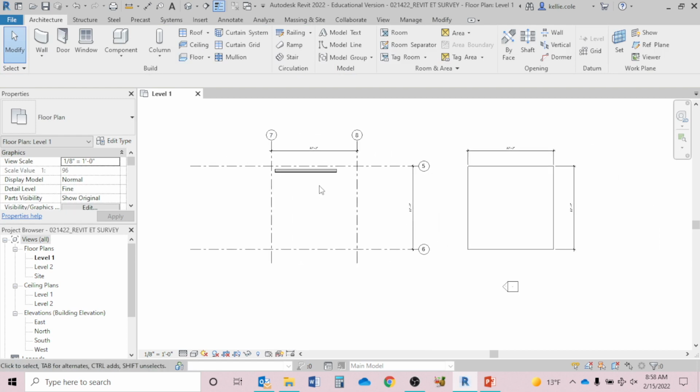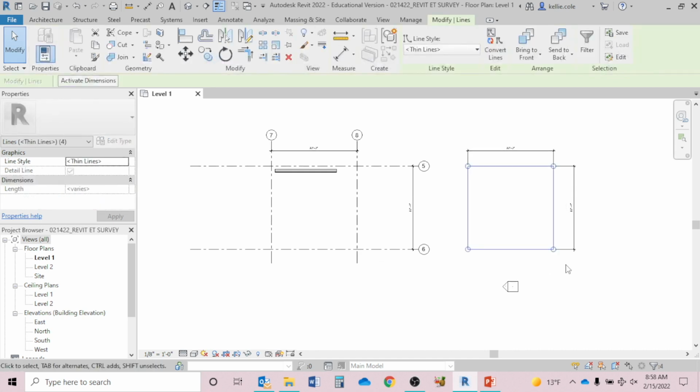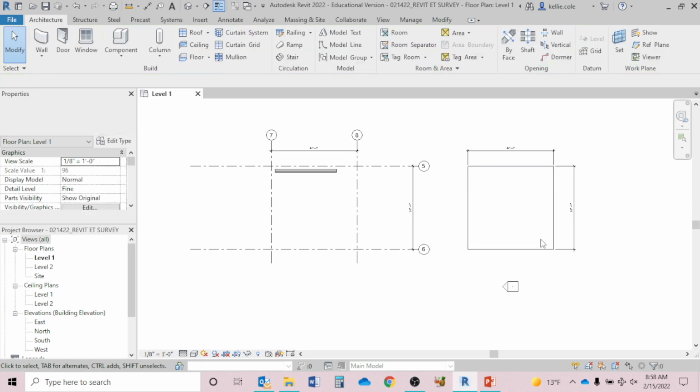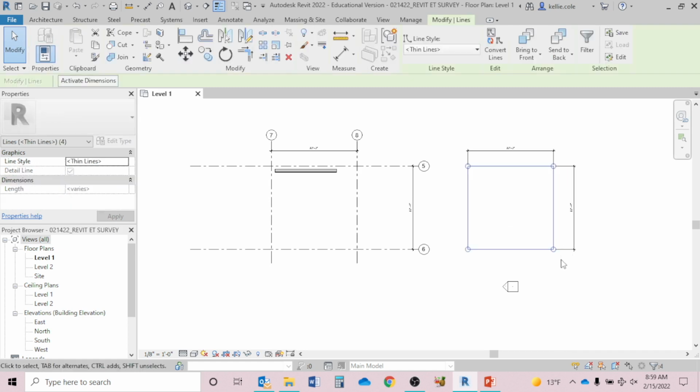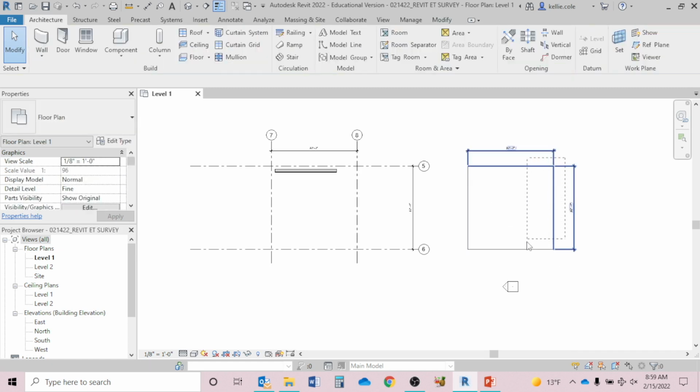So you could use grid lines, or you could use this rectilinear that we drew with detail lines, DL. In either case, once we have a set drawing, let's say I don't want to move it. I'm going to pin this to my page. So first select the items. Again, to select something within the middle of your selection tool, click left, drag right. If you want to select everything you touch with your dimension tool, click right, drag left.